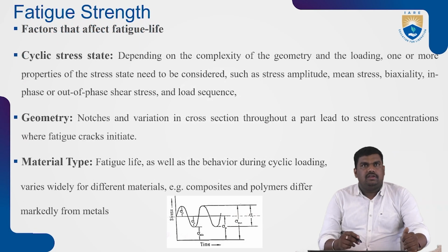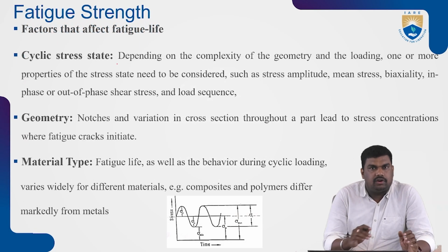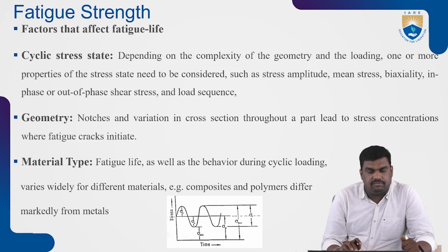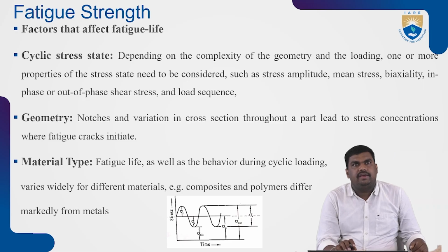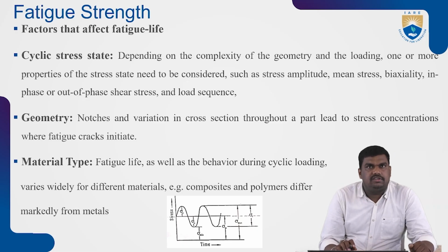So fatigue strength, cyclic stress state. Now a few parameters, how they are affecting. Cyclic stress state: depending on the complexity of the geometry and the loading, one or more properties of the stress state need to be considered, such as stress amplitude, mean stress, biaxiality, in phase or out of phase shear stress, and load sequence.